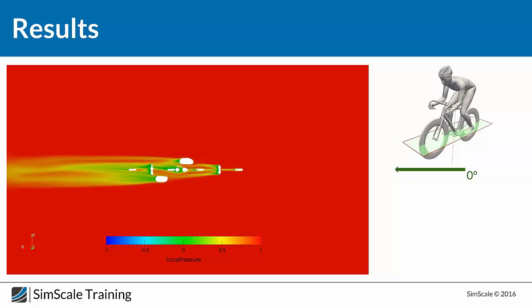To do this, you need to change the profile of the flow, and to change the profile you have to create a turbulent boundary layer. This will increase tau, the wall shear stress, and make sure your flow has more tangential effort to stay attached over the surface for a long distance.